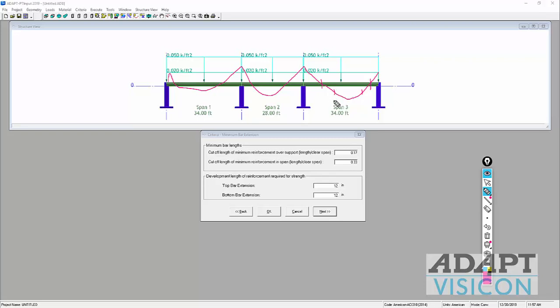So this is, let's say, the bar that meets the maximum demand, and then we might need additional bars here where this area of steel 1 plus area of steel 2 meets this moment. At the cutoff point, we extend this by this distance, 12 inches, and then the extension for this longer bar here meets this moment at this location here.